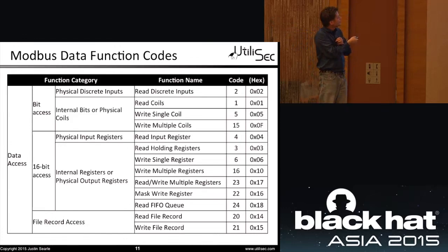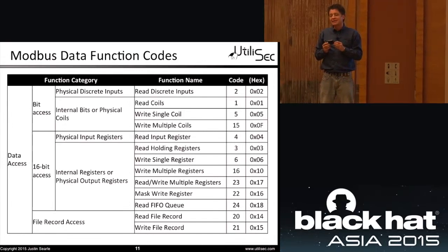Okay, so that's all our digital. So this is digital in and out. All of it is bit level access, 1s and 0s that we're sending. Now if you want to talk to an analog input or an analog output, analog is what we call registers. Analogs, by default, will be 2-byte values, or a word is what we usually call it.